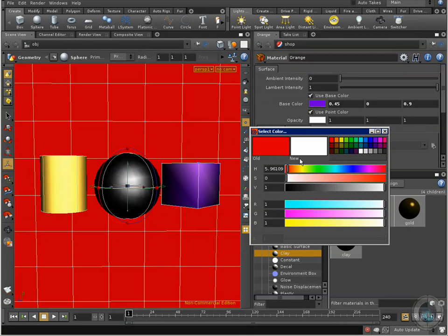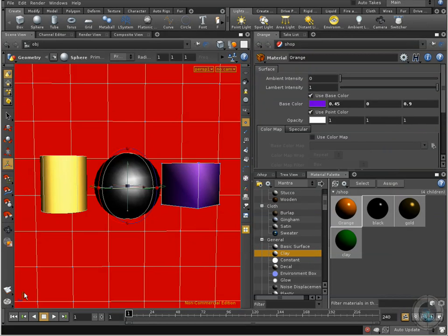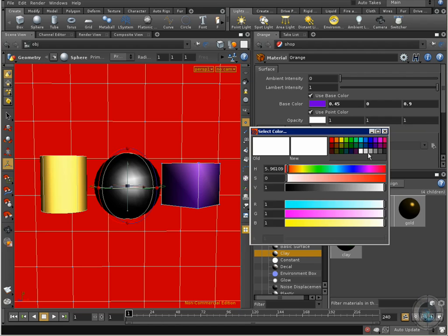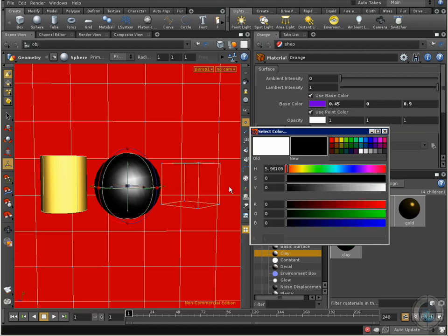This is the shading of our OpenGL. But if we create a preview, we are going to see better results. Well, opacity means transparency, and transparency means alpha channel. White means opaque and black means transparent. If I set that to black, you can see that now my color is transparent. I can see the cube here, but I don't see the material because now it's transparent. And that's what we can do with this parameter.